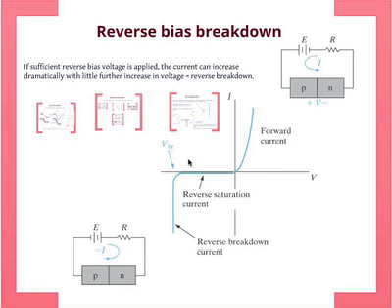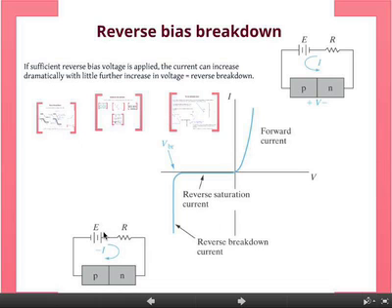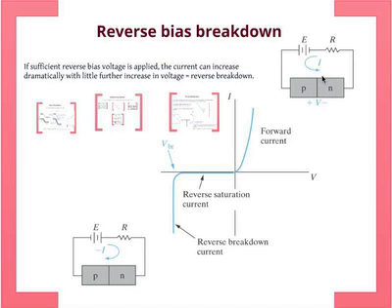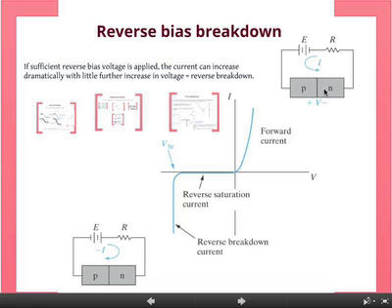So first of all, that's what's shown here. You see the reverse bias current here, forward bias current here. The first question is, under forward bias, you know that the voltage across the junction is very small. Remember, it's basically the contact voltage minus the applied voltage, V0 minus V. So this drop here is very small, which means that the current is basically determined by this resistor, right? Imagine that there is 0 volt drop, and the current is what? V over R, right?